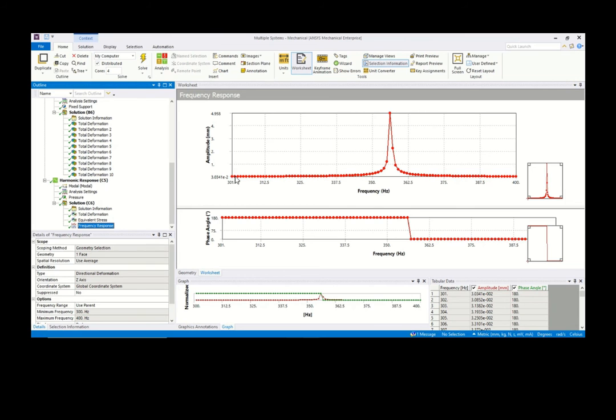So you can see the effect of frequency. At 300, because it's still far away from its first natural frequency at 356, you have a displacement or deformation of around 3 power of -2 mm. But when it goes near 356 itself, it can go up to 5 mm.